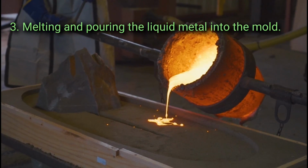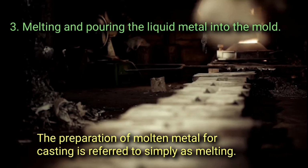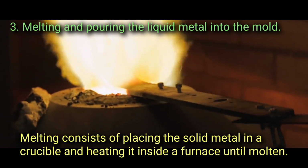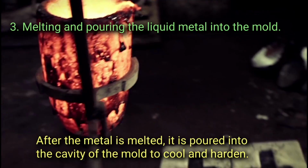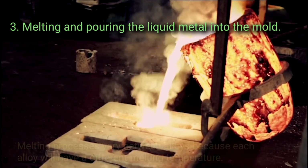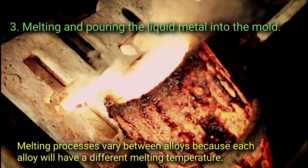3. Melting and pouring the liquid metal into the mold. The preparation of molten metal for casting is referred to simply as melting. Melting consists of placing the solid metal in a crucible and heating it inside a furnace until molten. After the metal is melted, it is poured into the cavity of the mold to cool and harden. Melting processes vary between alloys because each alloy will have a different melting temperature.